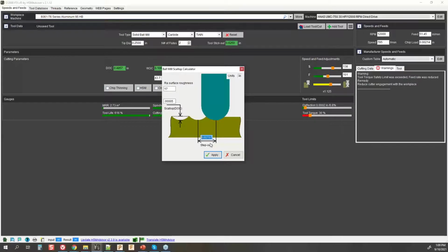And usually we'll cut down to about 2 to 5 thousandths in the industry. I see that quite often, depending on the size of your cutter, just as a basis so that we can be sure to get those surface finishes. Now, these calculators do a decent job, but of course, we've got length of the tool to consider, as well as RPMs, type of material, all the different factors that are still in play here.